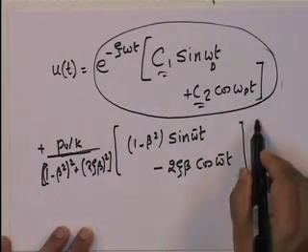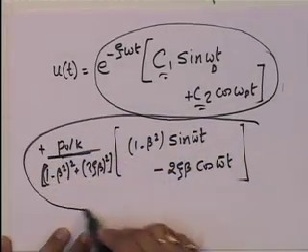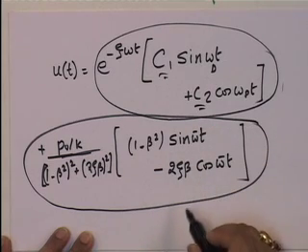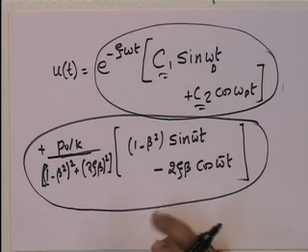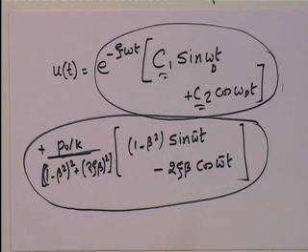And if you look at this part, what does this part depend on? This part depends on P naught by k, which is the equivalent static peak displacement. Remember P naught is the peak amplitude, so P naught upon k is the peak equivalent static response.